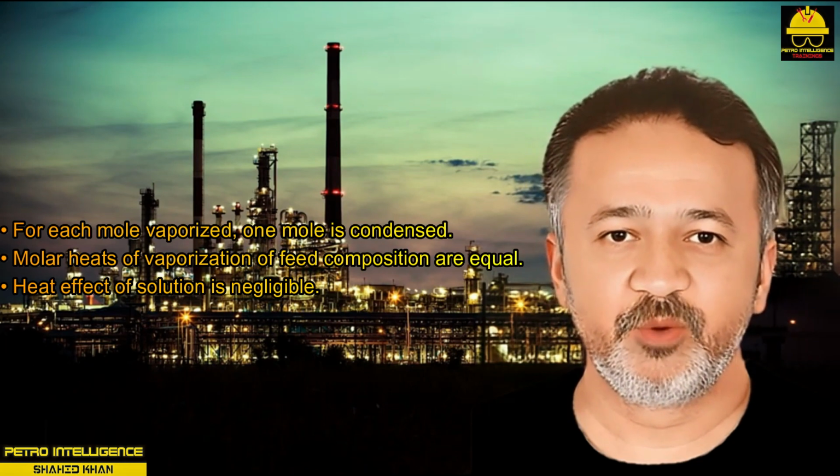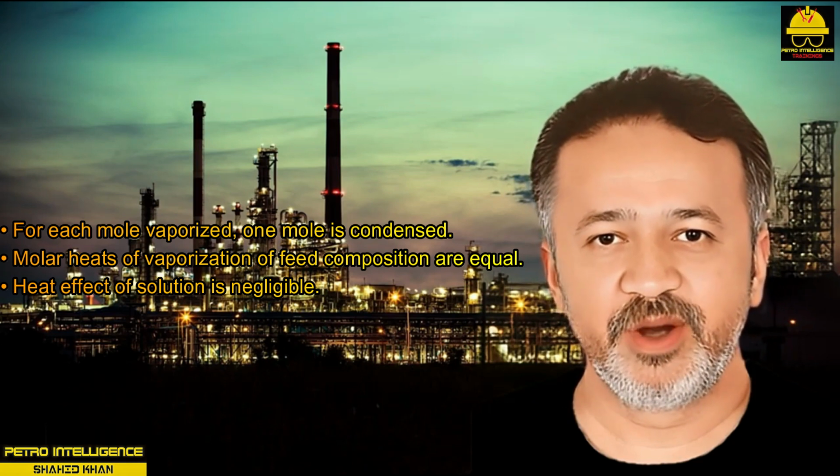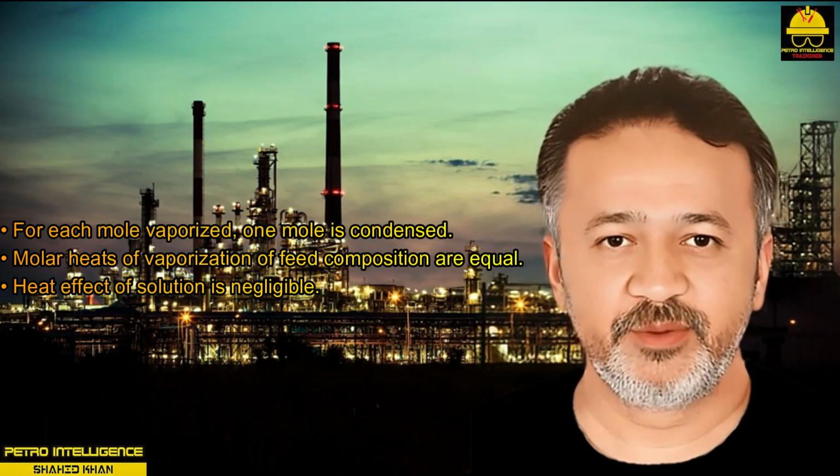This method is based on the assumption that there is a constant molar overflow that requires the following. For each mole vaporized, 1 mole is condensed. Molar heats of vaporization of feed composition are equal. Heat effect of solution is negligible.